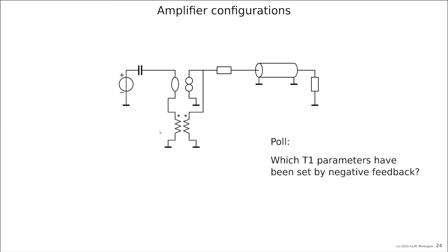B of the amplifier is definitely set because the output impedance is set by the resistor added in series with the output of the amplifier. But this is a brute force technique because at the output of the nullator you will find 0 ohm because we have parallel feedback there. So we have 0 ohm at the output of the amplifier, and then we place a resistor, in this case 50 ohm, in series with it, to create an output impedance of 50 ohm. So indeed, B and A of the amplifier will be fixed, but only A will be set by means of negative feedback.